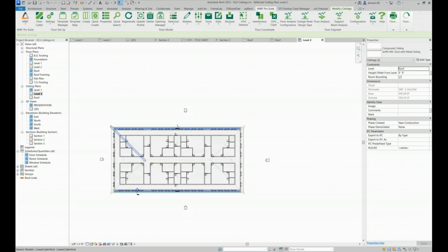because with this, you can place a continuous member. It doesn't break that member into mini pieces. So if you have a continuous T grid, great, it will work perfectly, but it doesn't create that cross for you, so it doesn't create the grid in the other direction. You'll have to add the other direction as bridging because you cannot have two panels within the floor, unlike with walls. With walls, you can have multiple panels inside the same wall. With floors, you cannot do that.